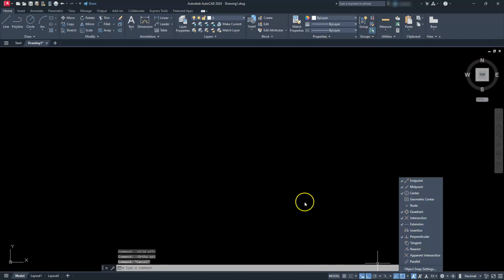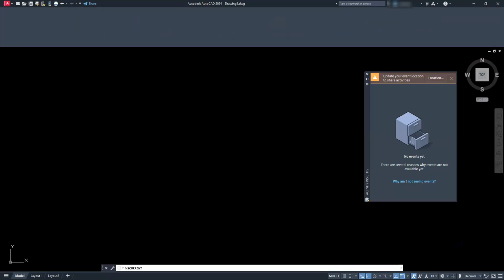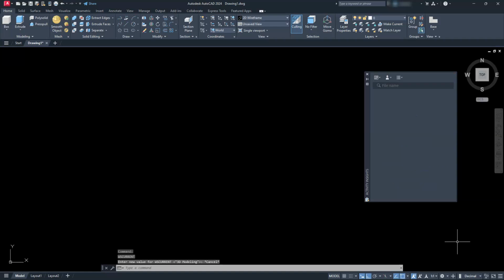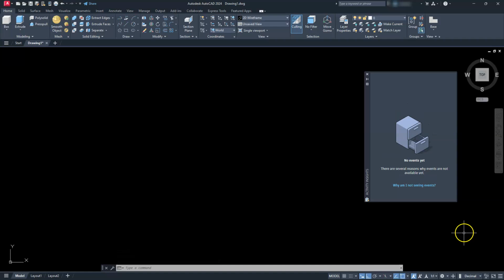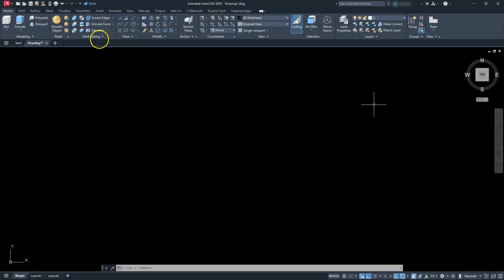All right. Let me switch over to 3D AutoCAD just by selecting the little gear here, and then I'm going to select the 3D modeling. Now sometimes you can knock out a lot of steps by creating the polyline first, or you may create them with lines and then join them later. But that's going to be strictly up to you. All right, so I'm going to go with the polyline option this way.